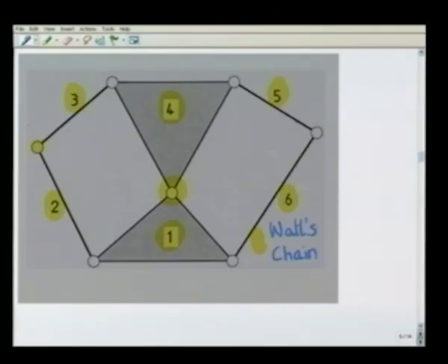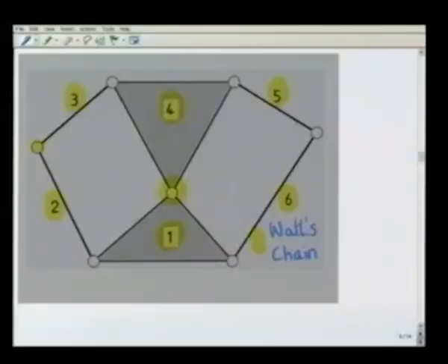So, in a Watt's chain, 2 ternary links are directly connected to each other. In this Watt chain, we can see that the 2 ternary links, that is number 1 and 4, are equivalent, in the sense both of them are connected to a ternary link at one kinematic pair and two binary links at the other 2 revolute pairs.